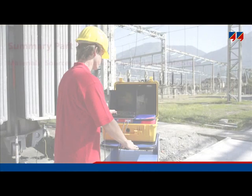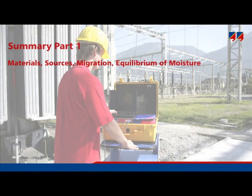This section covered the materials used in the insulation structures of transformers, sources of water, including how migration and equilibrium work, the fact that moisture equilibrium is caused by differences in relative saturation, and that moisture equilibrium aims to have the same relative saturation in adjacent materials. An explanation that water is an aging product, which also accelerates the further aging of a transformer.